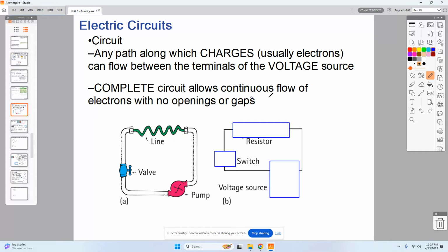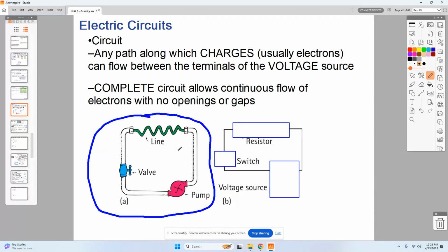We'll often use a mechanical analogy to understand electrical current flow, simply because most people in general are more familiar with the mechanical side of things than the electrical side. So a pump is like a pressure source for a mechanical system. The equivalent for the electrical would be a battery or a generator. I'm going to show you what that would look like using the schematic over here. If I'm going to draw a battery, it looks something like this. The small size and the large size represent different cells within that battery, and that would be a symbol for an electric battery.